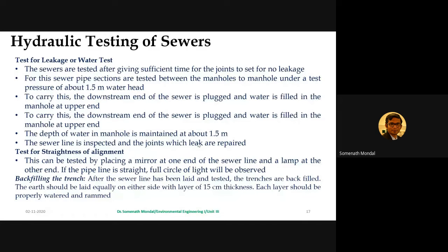And if it does not happen, that means there are some obstructions existing within the pipe, and that has to be taken care of. Now, in the absence of any obstruction, what will happen is, sometimes your mortar is projecting in the joints, and those things are fine, but those things cannot stop those balls. So the balls shall roll down the invert of the sewer pipe and emerge at the lower end.